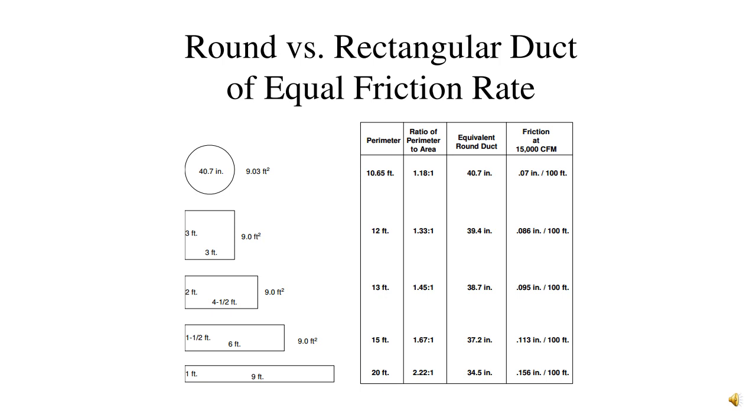For example, if you know the CFM and you know the equal friction rate, then you can choose the round duct size or the equivalent rectangular duct size by using a duct calculator, or as we always mention, ductulator. Or you can also choose, if you know the CFM and know the velocity, then you can also choose the size for round duct or equivalent rectangular duct.